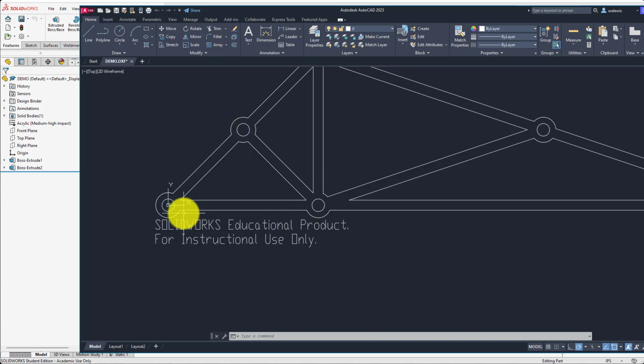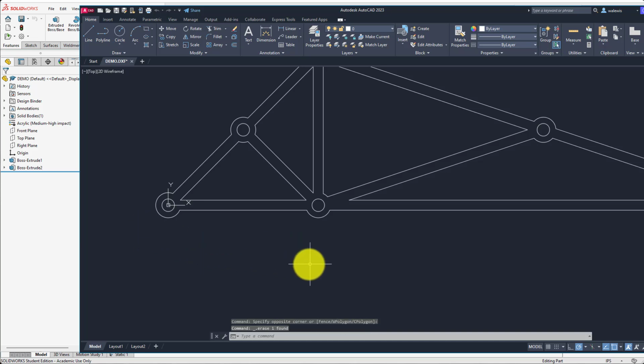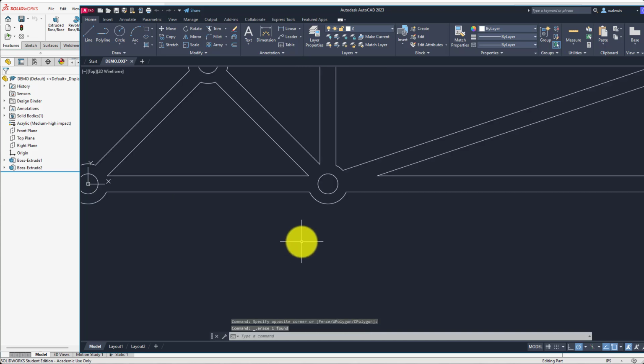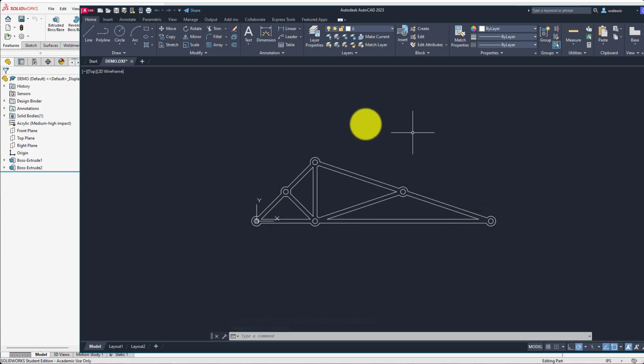One of the things that this is doing is our laser is just going to follow these lines and cut this part out. It can't change the thickness of members, so we can't come in here and lighten one member, make it thinner. It's just going to be a profile cut. It's going to cut these holes out and then come out here and cut the middle sections out and then cut the outer frame out. Things that we'll end up ditching for you guys is this stuff right here, the SolidWorks instructional stuff, because we are using an educational version of SolidWorks. It always puts that on there, so we just have to go in there and manually delete it for you guys. But don't worry about doing that. That's something that we'll do on our side, and then we'll import this into CorelDRAW and into the software the machine works with, and we'll cut your parts out.